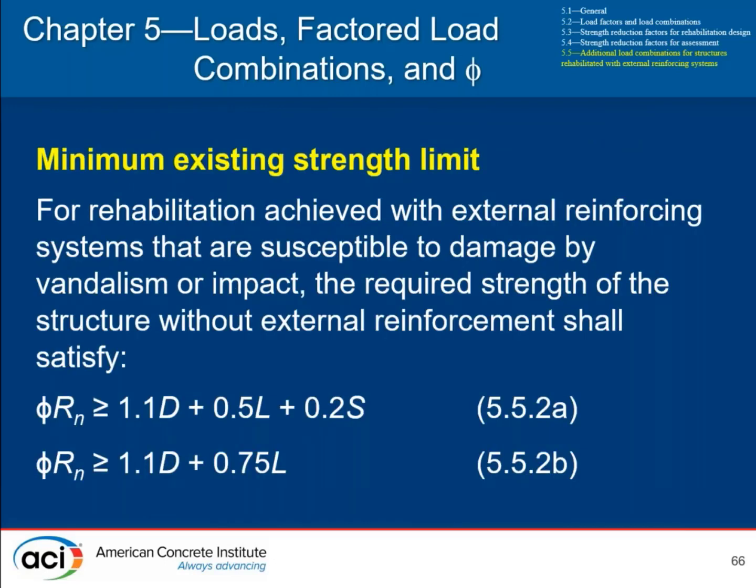The provisions are as shown here. For rehabilitation achieved with external reinforcing systems that are susceptible to damage by vandalism or impact, the required strength of the structure without that internal reinforcement shall satisfy these two factored load combinations.